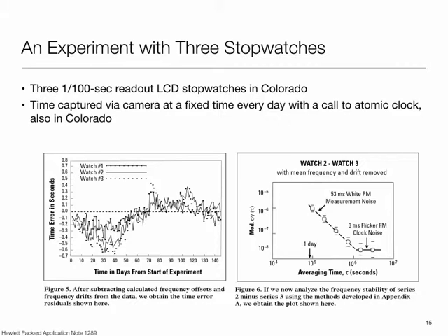If your clocks are very stable, then even if they are erroneous in the sense that their frequencies are different, you can learn that offset and then relatively infrequently revisit your synchronization. If, on the other hand, clock frequencies are changing quite frequently because temperature is varying a lot, things like that, then you have to do that synchronization much more frequently.